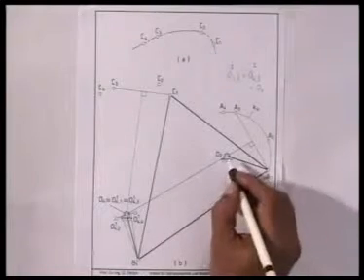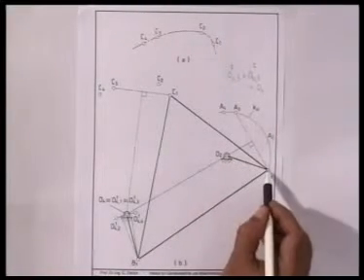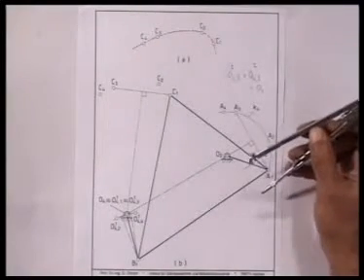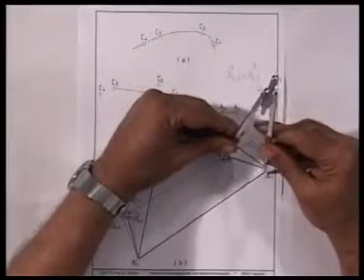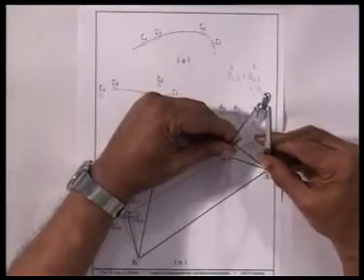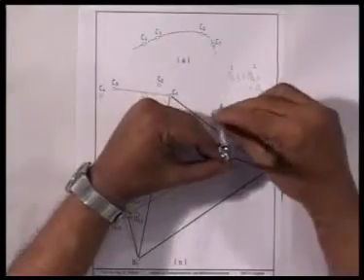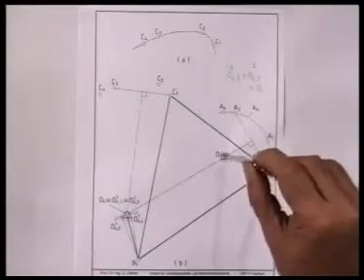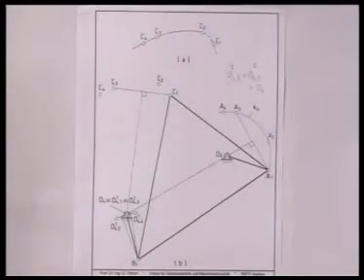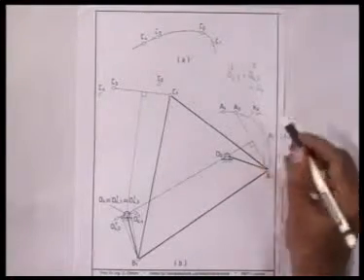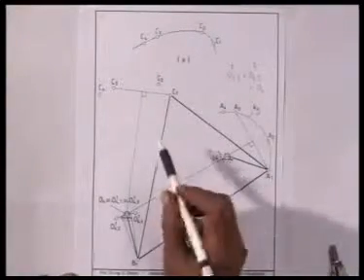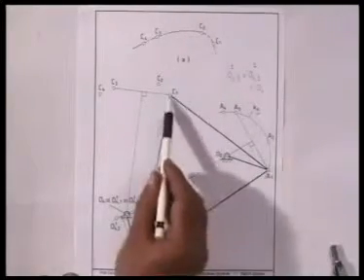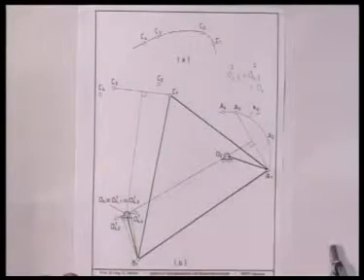To solve this problem, as before, I choose O2 and A1 arbitrarily. So the path of A1 I can draw with O2 as center and O2A1 as radius. It is this circle. This is the path of A, which I have marked as KA. So C1 is given to me, A1 I have chosen arbitrarily, so I know this rigid length, namely AC.